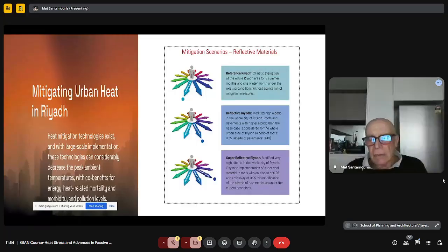But actually, in non-humid climates, the atmospheric window is quite open. So these supercool materials, apart from the very high reflectance they present, have another benefit: they emit only at the specific wavelengths of the atmospheric window. So they dissipate all the excess heat directly to space. We send the excess heat of the materials, of the city, if you like, directly to space. And this is the reason that the thermal performance of the supercool materials is much superior to the thermal performance of the conventional cool materials.